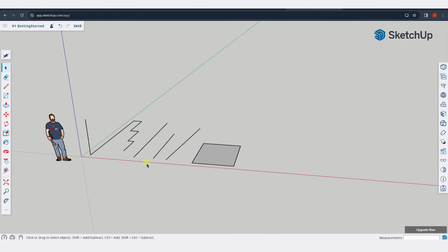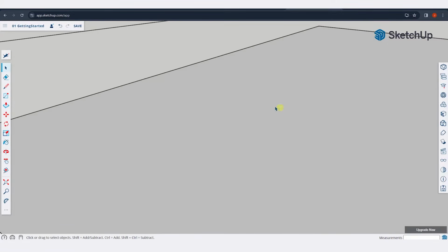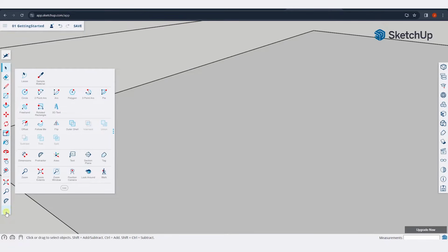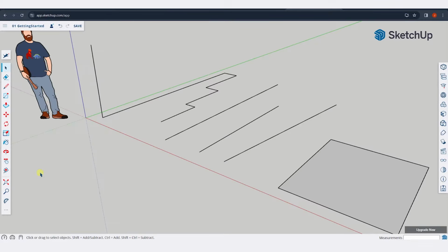And so just real quick, it is easy in a 3D space sometimes to get turned around and lost and have trouble getting back to something that you actually recognize. There is a tool in here which I really like called Zoom Extents. So if you ever get so far into your model that you can't get out of it, just come over here and click on the Zoom Extents button. That'll zoom your camera out so that everything in your current model will be visible in one window. So that's a good way to reset your viewport.